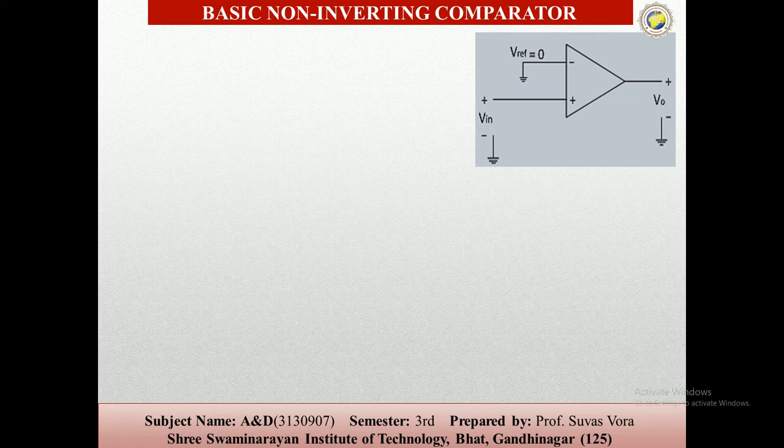The inverting terminal is grounded, so the V reference is equal to 0. Here the input voltage is denoted by V in, while the voltage applied to the inverting terminal, with which V in is compared, is denoted as V reference.